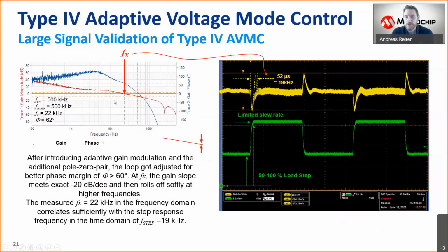So we've heard it before. If you have a region that shadows out close to 0 dB, then the step response frequency you might find might be affected by that lower frequency flat region. But in this particular case, the gain is still high enough so that it doesn't influence our step response. So the step response we see here is truly the 20 kilohertz we have adjusted here as a crossover frequency.